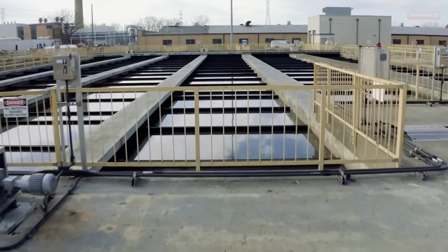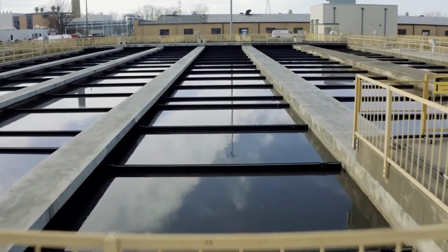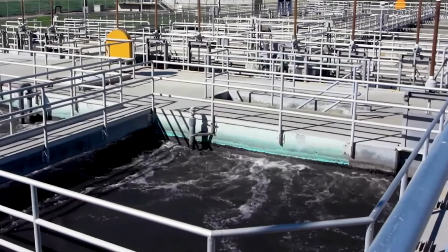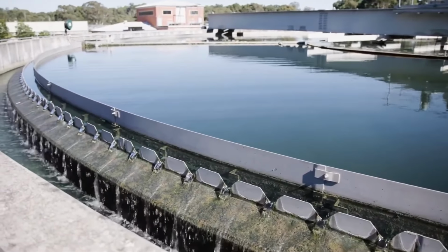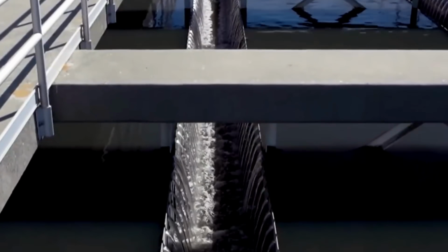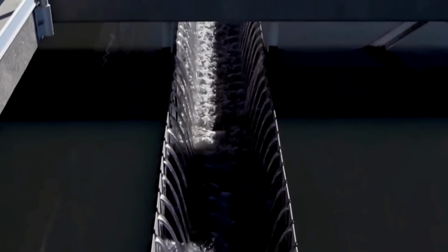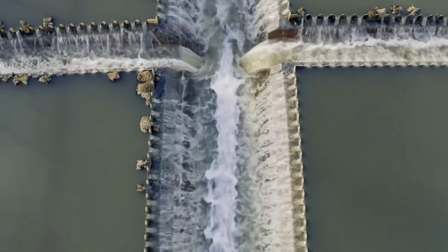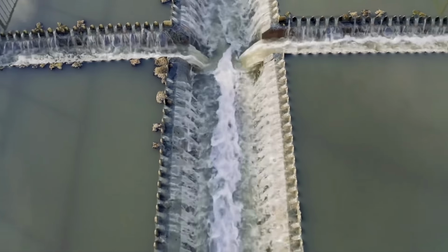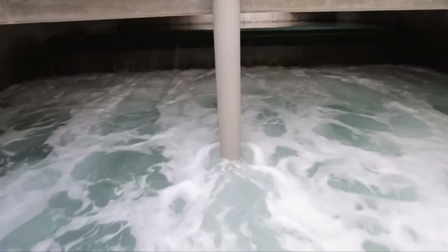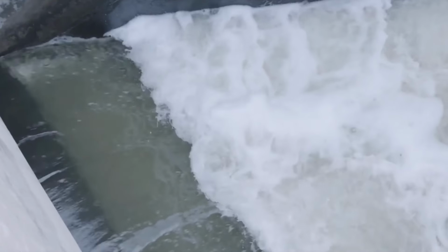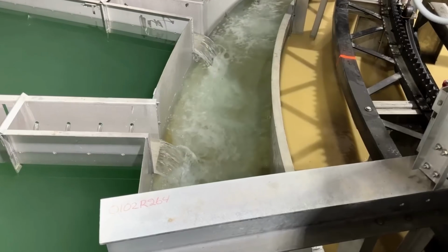The plant therefore moves into post-treatment. Depending on the facility, calcium and alkalinity can be restored by passing the water through limestone or by adding carefully controlled mineral compounds. The pH is adjusted so the finished water is less corrosive to pipes and storage systems, and disinfectants are added to control microorganisms as the water moves through the distribution network.